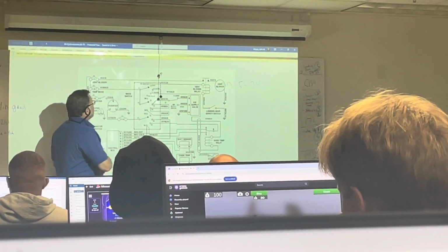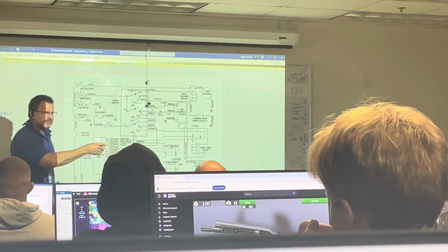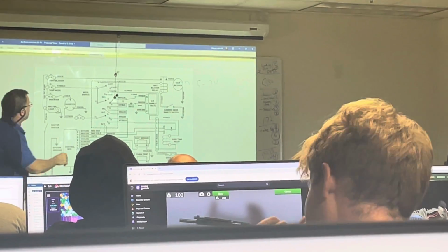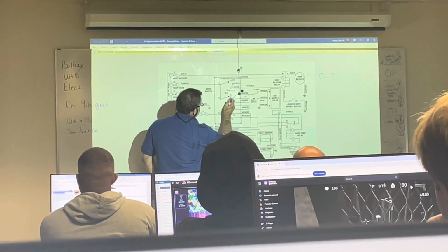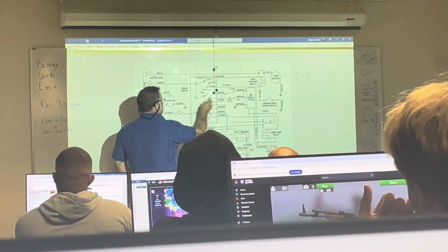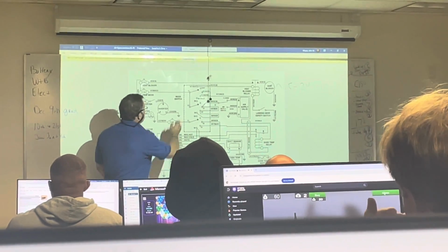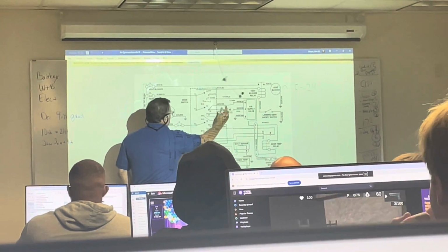And it has a vent, it has an off, and of course all electrical diagrams are in the off position, aren't they? On the non-power position. So, we have an off, we have an off, we have an off. These 2 poles are off. It's one selector with 3 rows of wiring that are behind it. That's why it's all in this silhouette, to show you that's one component but 3 rows of wiring.